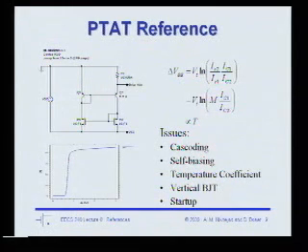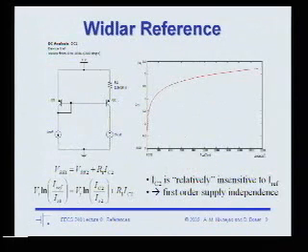Okay. Another way of looking at this is that the circuit kind of bootstraps itself. The whole problem in the previous circuit is that the reference current is a function of the supply voltage. So instead of using a reference that depends on supply, why not use the output of the circuit as its own reference? It's kind of a funny concept: take the output of this circuit, mirror it, and make it its own reference. Then it will not depend on any external reference, and it won't depend on supply voltage.